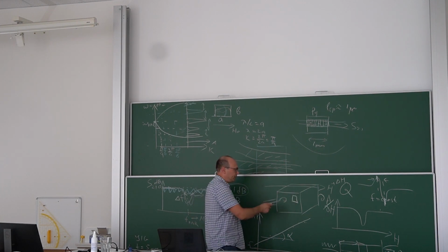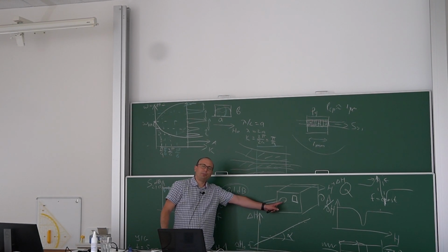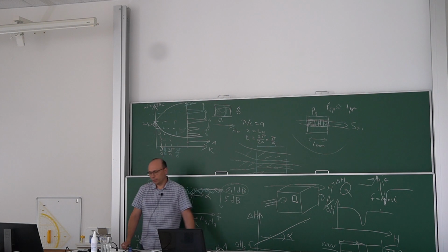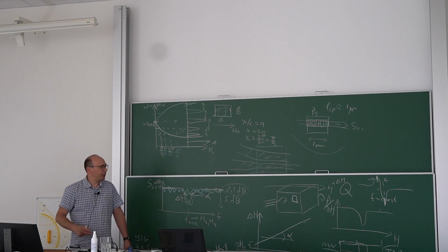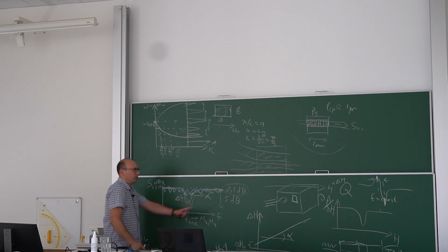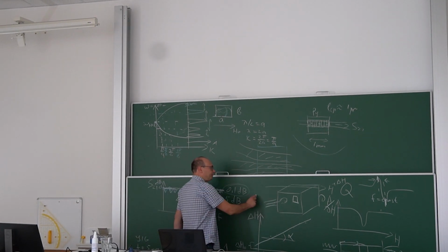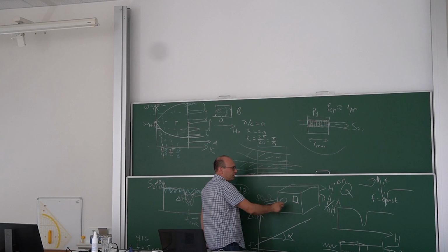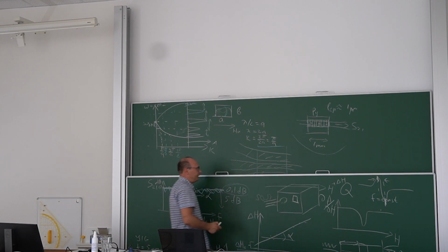So you just bring such a coaxial loop and you excite it. You can make this loop bigger, smaller, you can put it in different positions. You can change the strength with which you couple your 50 ohm transmission line, just a coaxial cable, to the cavity.